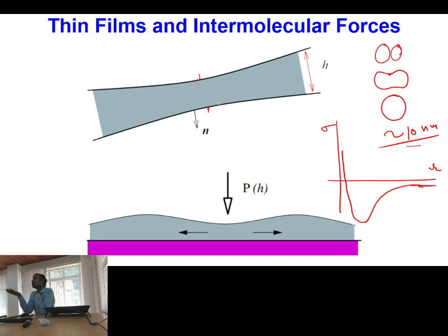But your computational solver is not supporting that. Okay, because as per computational solver, once your interface gap is less than one grid size, then immediately in the next step that will be merging with each other. So you will not be able to make a correct estimate of the time which is taken by bubbles to merge and form a larger bubble. Is this one clear? Because physically that is repelling, but your mathematical model is not able to account for the intermolecular attractions or repulsions. Okay, so sometimes what we need to do, we need to give some additional terms in our governing equations to model such situations.